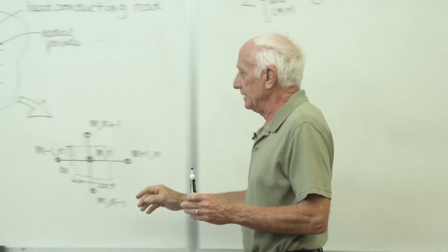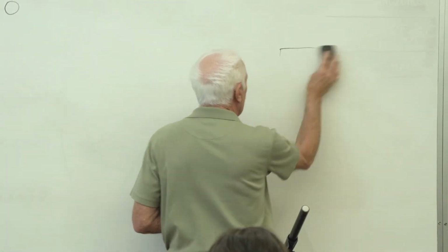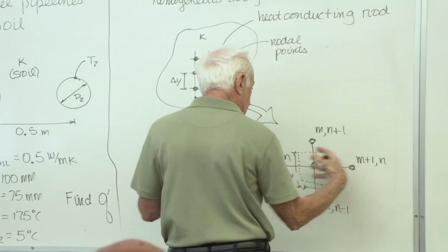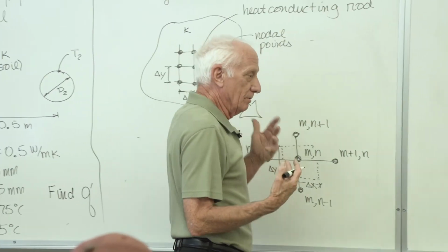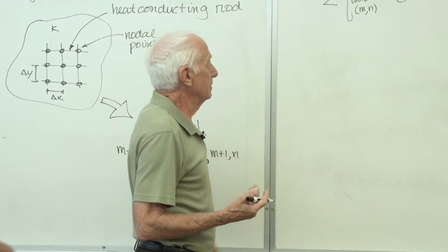So whether it's DC circuit theory or whether it's heat transfer, the same rule applies. If you don't know which way the heat goes, assume the sum of all the Q's into the node is 0, and later on, your math will tell you if you're right or wrong.